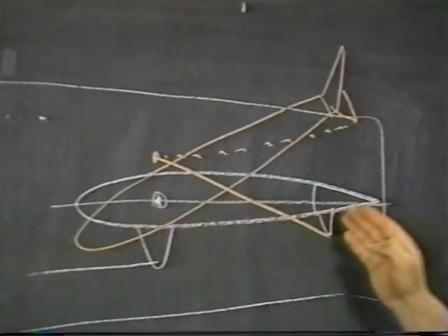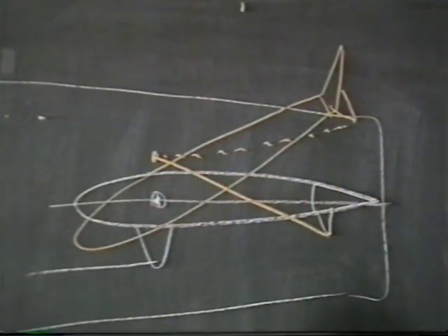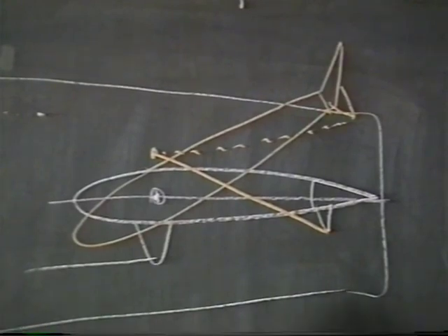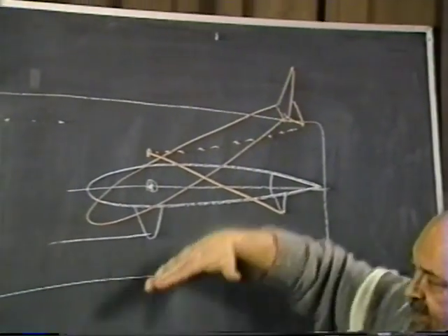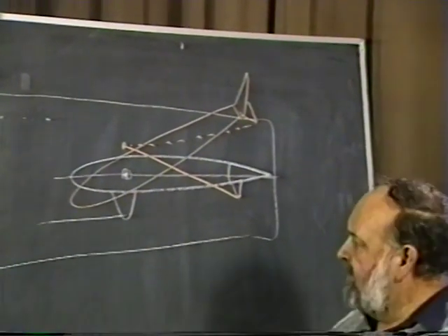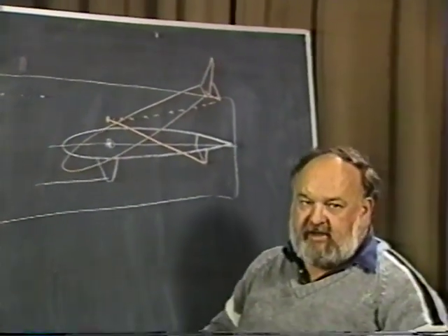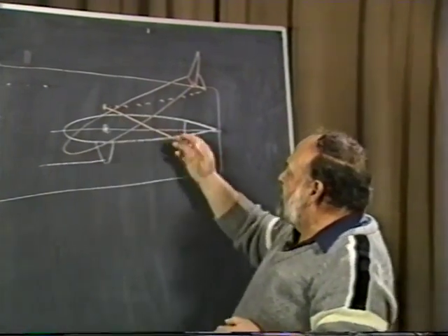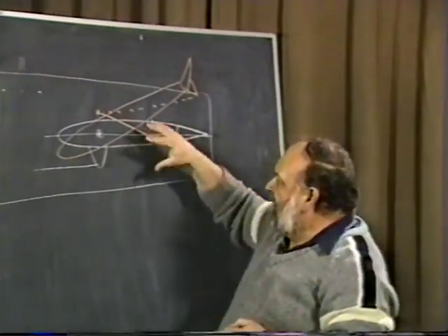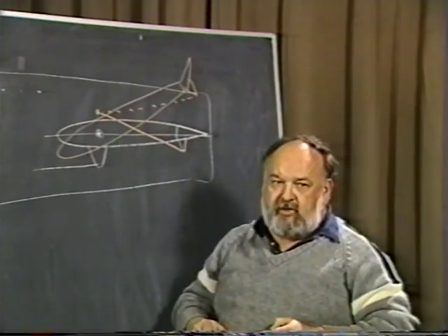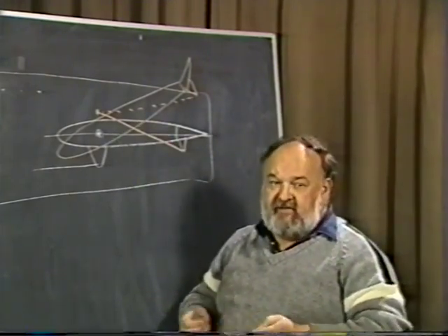You have a surface that is perfectly balanced and stable by itself, so when it's flying through gusty air, the tail does not tend to move compared to the airplane, and therefore it acts always as a fixed surface and gives you your stability. But at the same time, when you do want to move it and you actually physically move the horizontal tail, your servo tabs, anti-servo tabs in the back, add the proper forces around the quarter chord, around the pivoting point, and give you the feel.